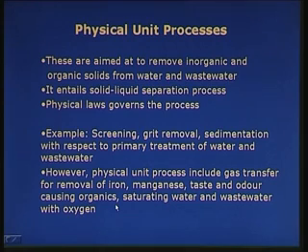And also, we try to saturate the water and wastewater with oxygen, because if oxygen is present in water, it is very pleasant, a pleasant feeling we will get. So, the wastewater also is saturated with oxygen by gas transfer. When this oxygen enters into the wastewater, what does it do? It supplies the oxygen to the microorganisms. The microorganisms utilize the organic matter and then produce carbon dioxide and water. The pollution is removed. So, that is what normally we do with this particular thing.